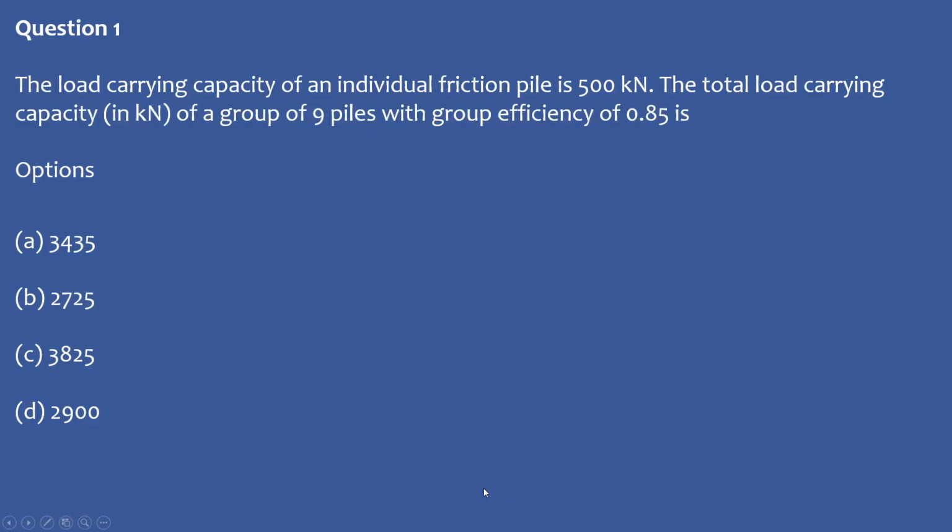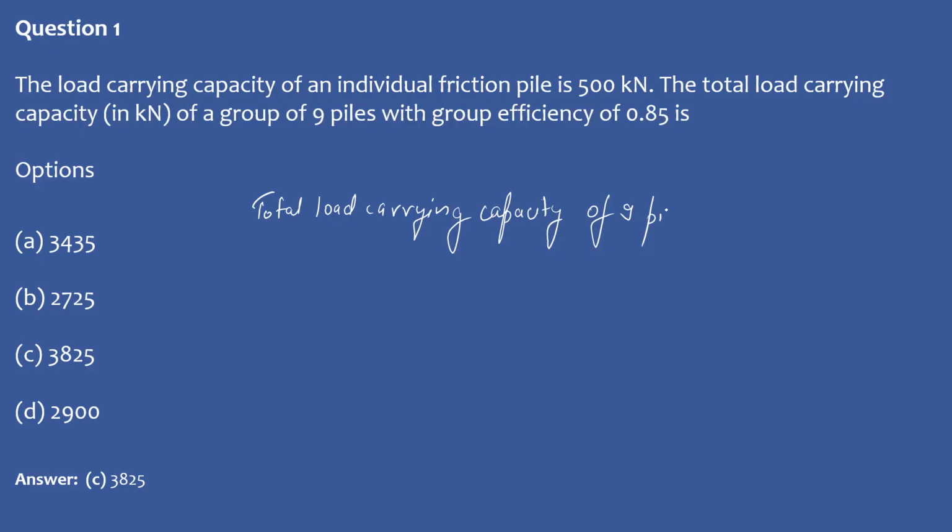So let's check the answer. The answer is 3825 kilonewton. The total load carrying capacity of 9 piles is 0.85 into 9 into 500.